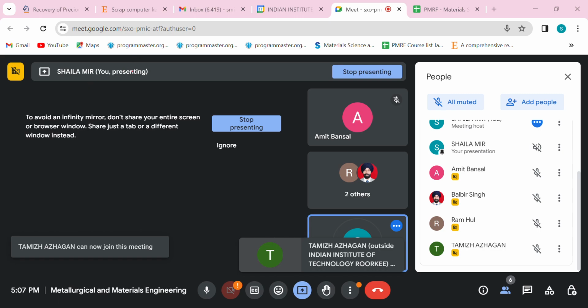You have three stages of creep: first stage, second stage, and third stage. You have to say whether the creep rate in the tertiary stage decreases, is constant, increases, or none. Obviously, as we have seen, this creep rate is increasing in the tertiary stage because it has overcome all the hardening in the material. At higher temperatures, the strains will accumulate in the material and result in fracture. So, the right option is C.